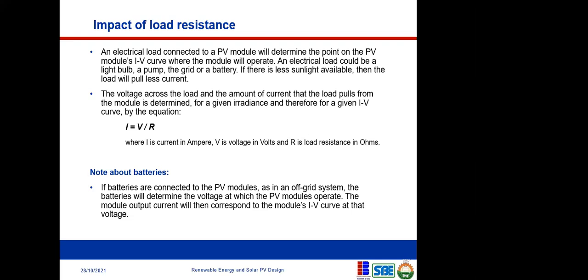Remember, we're talking about MPPT. That's why when you want to buy an inverter, you will see something like a label where they say it is an MPPT charge controller, right? That is for charge control that charges your battery. What that means is that it tracks the maximum point where you're going to get the highest power output from that panel, for whatever load, maybe for charging your battery or for the load that you want to power.